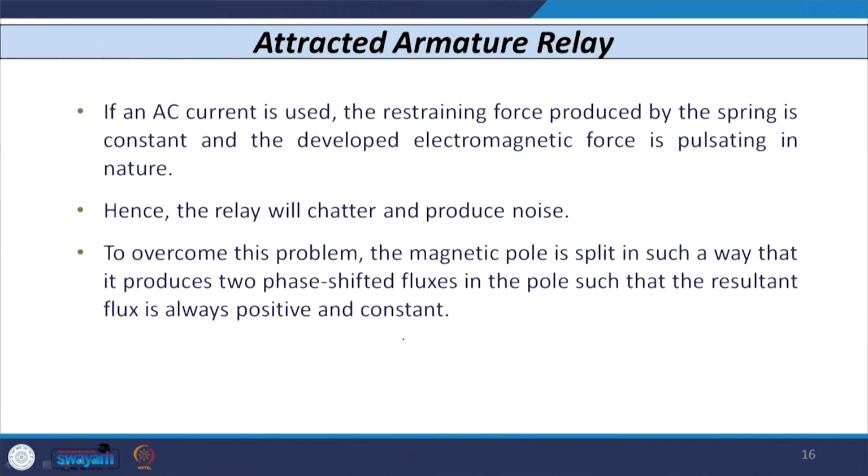Now, the main important point is that if I use AC quantities, that means whenever we give an AC supply to this coil, the restraining force produced by the spring is constant. But the force produced is pulsating in nature, because we are giving an AC supply and every half cycle the natural current zero comes. So obviously the relay will chatter and produce noise. That means the relay contact will sometimes be closed, then open, then closed again. So a chattering phenomenon occurs.